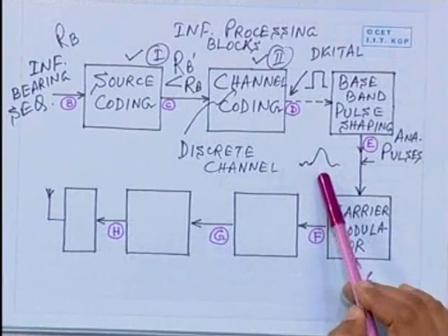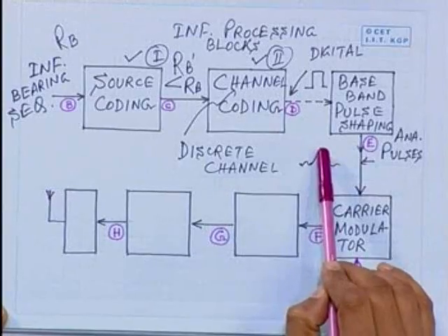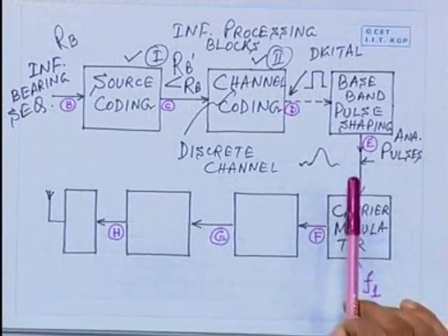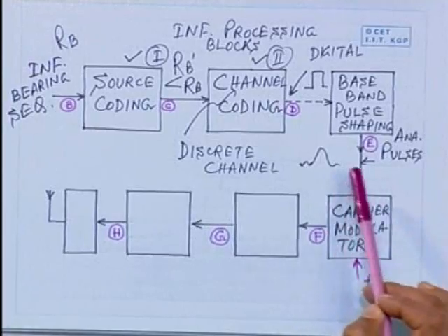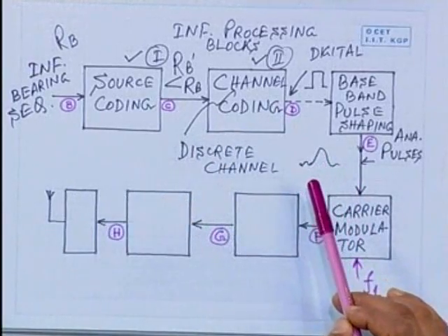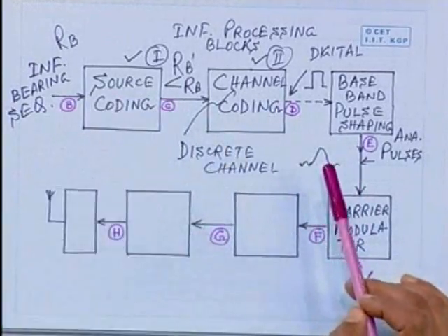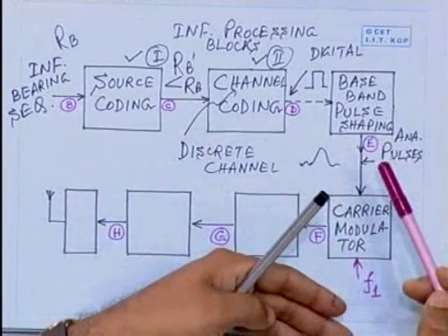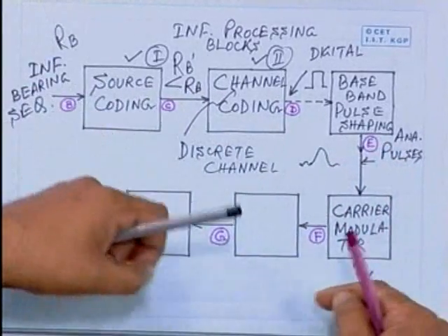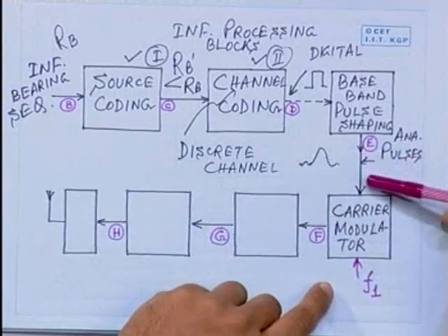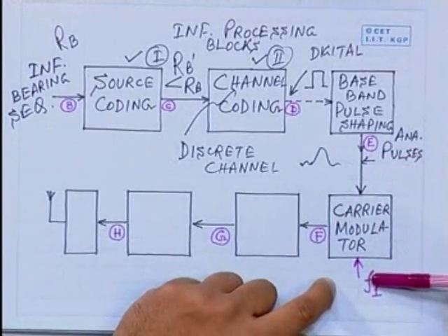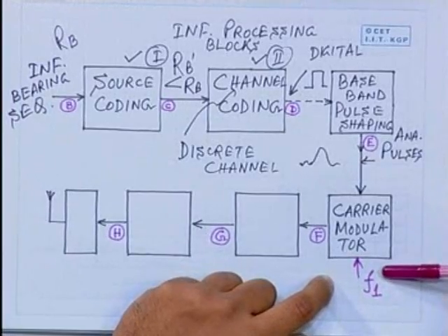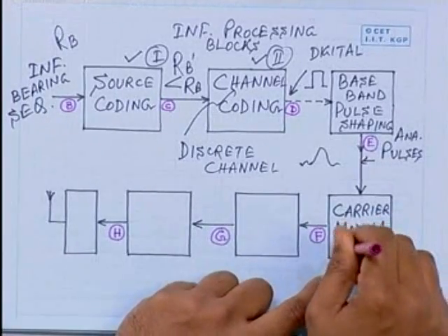What we will see later is that in a pulse, to get back our information somewhere in the receiver, we will be interested in one sample instant, one time instant in the pulse duration really. So the techniques for doing that have to be developed in the receiver. They are different from analog demodulation schemes. So there are many differences. New techniques will come in over there, but when it comes to carrier modulation, there is a similarity with analog carrier modulation also. But in implementation, there are differences.